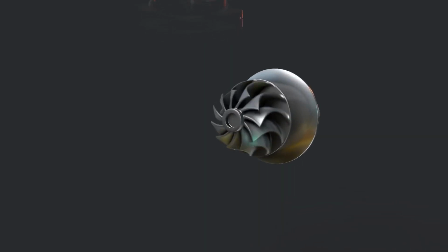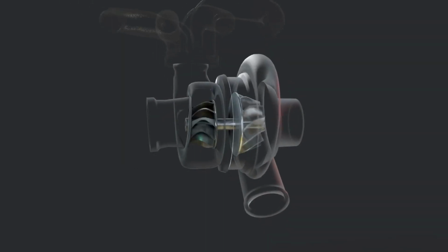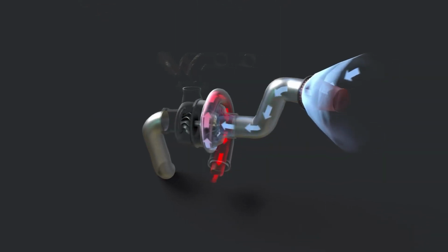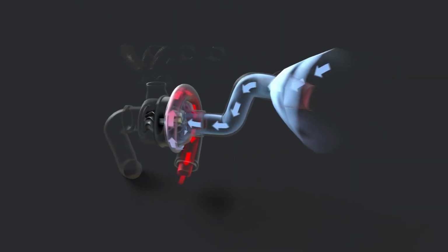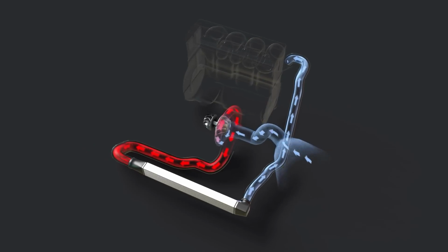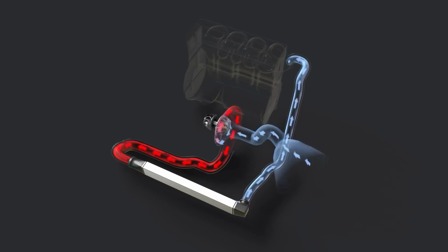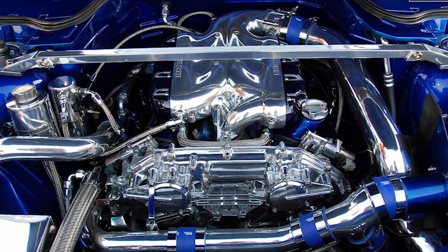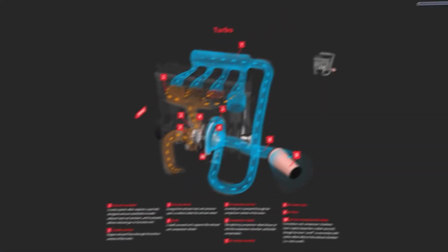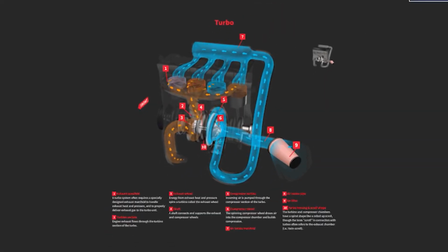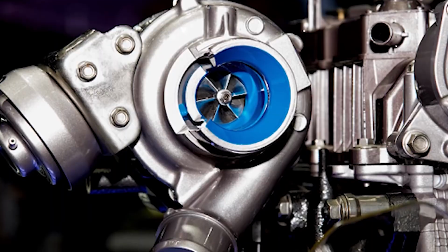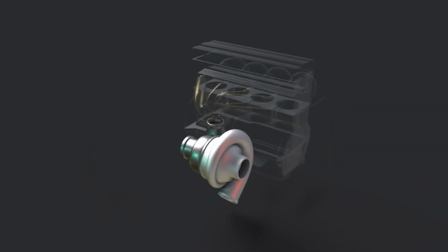This downsizing reduces engine weight and size, yielding benefits such as improved vehicle handling, better weight distribution, and more flexible packaging under the hood. Additionally, smaller displacement engines generally consume less fuel and emit fewer pollutants, helping manufacturers meet stringent environmental regulations. Turbocharging also promotes better thermal efficiency and reduced engine pumping losses, contributing to an overall advancement in fuel economy and emissions reduction in contemporary vehicles.